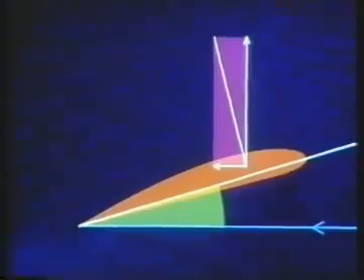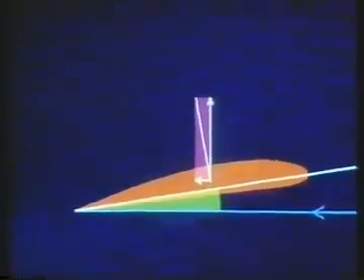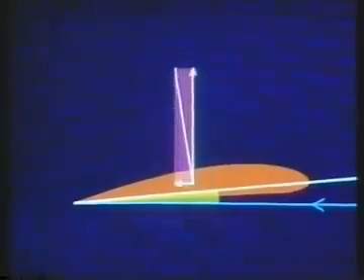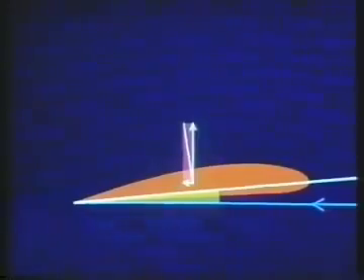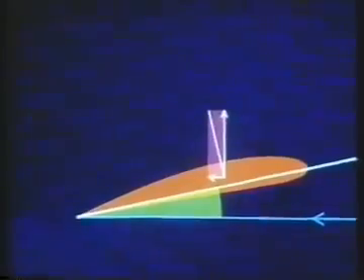We know that the amount of lift generated varies with the angle of attack. It also varies with the speed of the airflow. The faster the airflow, the greater the lift. And vice versa. So in order to maintain level flight, when pilots alter an aircraft's speed, they also have to adjust the angle of attack to keep the lift constant and equal to the aircraft's weight.